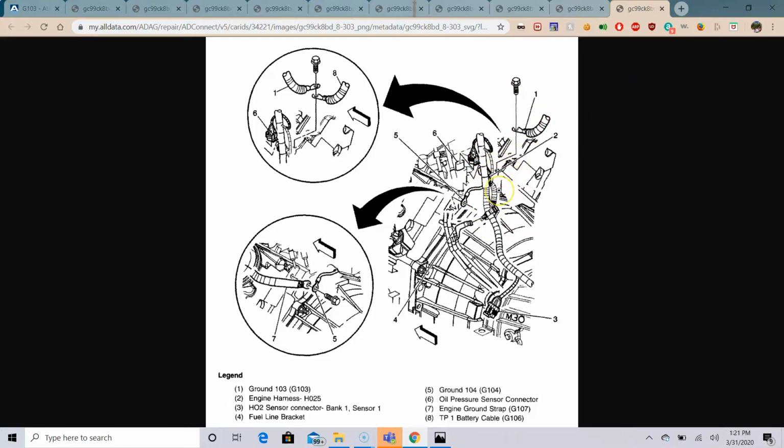Right, so just so you know, maximum voltage drop allowed, 0.1 volts, 0.1. So when you looked at that ground, when it cranked, when a full load of the starter was on it, it went like 0.252, something like that, which was excessive during that time. That's when grounds deteriorate.